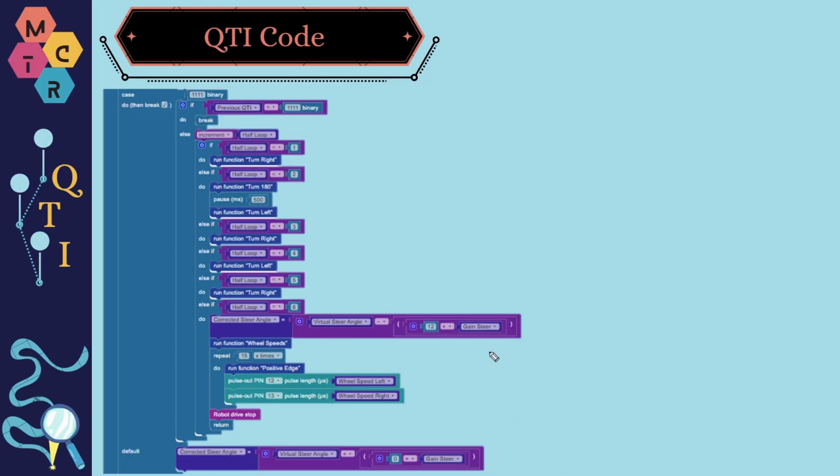A set of instructions were included in order to make the robot do specific actions depending on if it needed to go to the left or right, and it used a counter variable called half loop in order to give these instructions depending on where it was in the run. Once the robot reached the end and half loop was equal to 6, the robot would correct itself and make sure that it was at the starting point, and then the robot would stop driving, and the return function was used for the program to end itself.